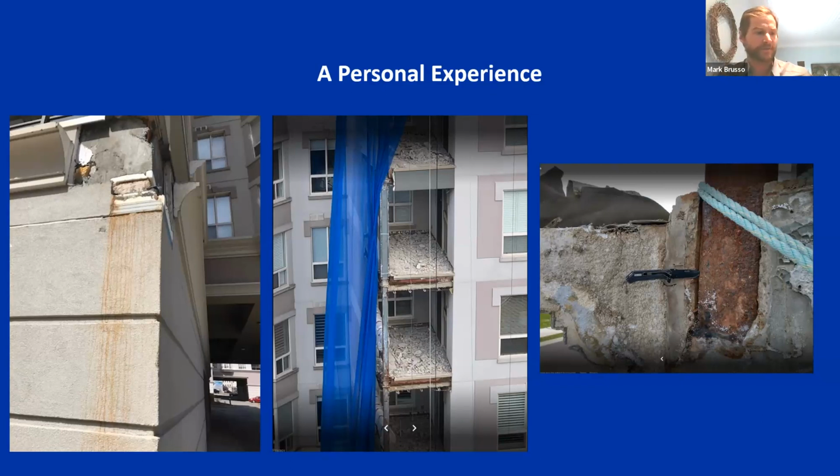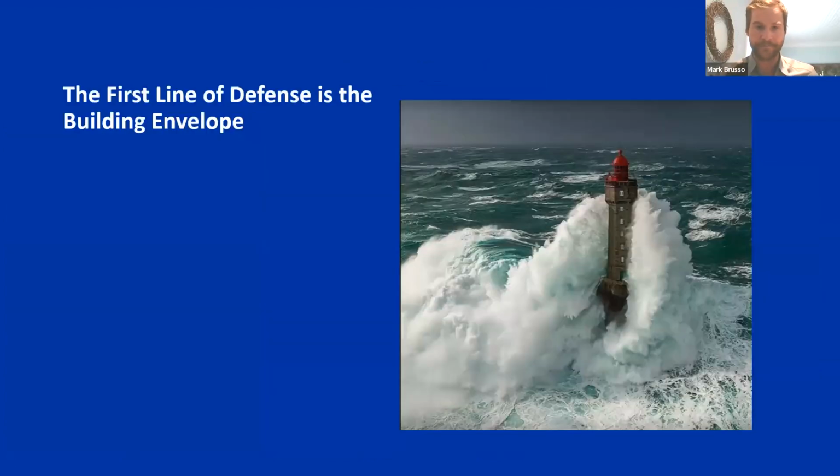So just to illustrate that, the functioning of a building envelope requires many components working in unison together, and even leaving out one small detail like a weep system can have humongous consequences. So building envelope, I always like to take a look at this slide and explain that it really is our first line of defense against Mother Nature.